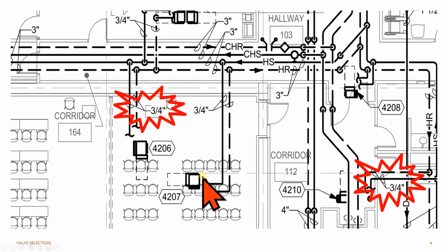If in case they haven't given you the line size, there might be specific notes in the drawing telling you that all the terminal units or equipment you're sizing for should have a specific line size given. If it is not given, you should get back to your mechanical people and get the line sizes clarified.